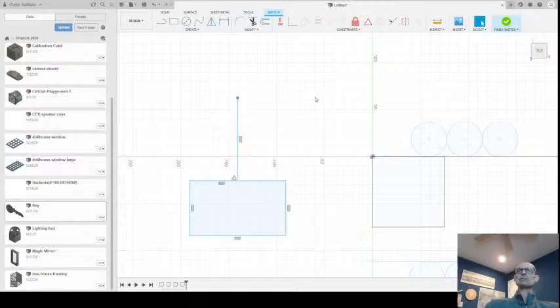at a 90-degree angle. Now we can remove those constraints. Well, I'll leave the midpoint, but we could also do something like a perpendicular, which ensures that these two lines are always at 90-degree angles to each other. And that ensures the line will be straight up and down because it's derived from a line that is completely horizontal, and we're saying we want you to be 90 degrees to that line.